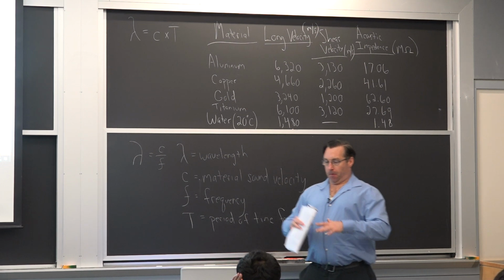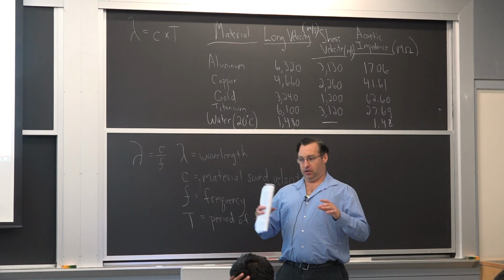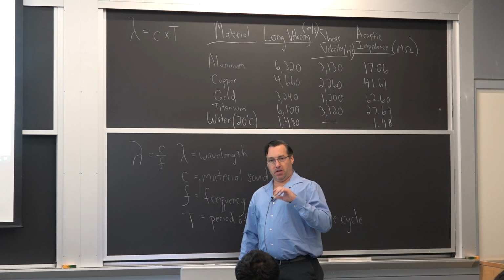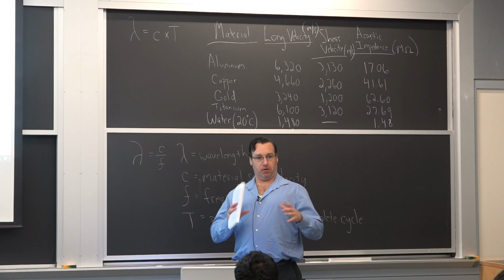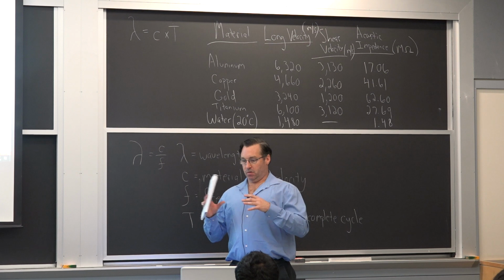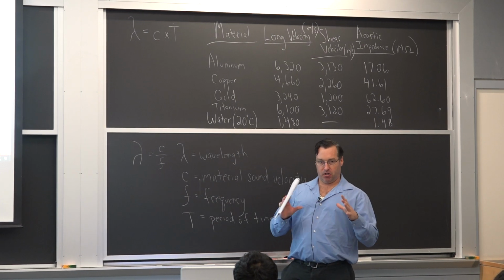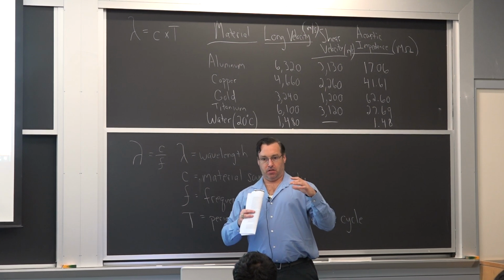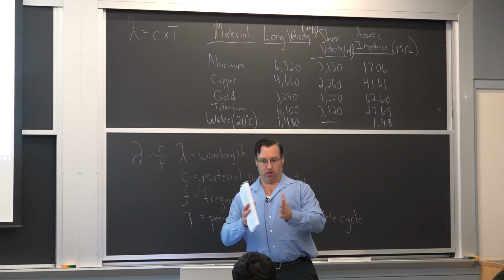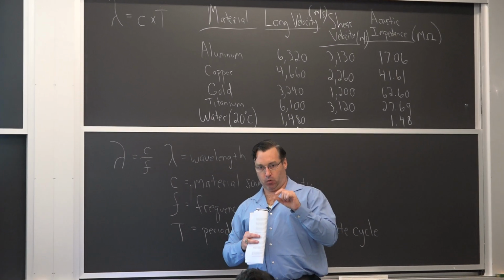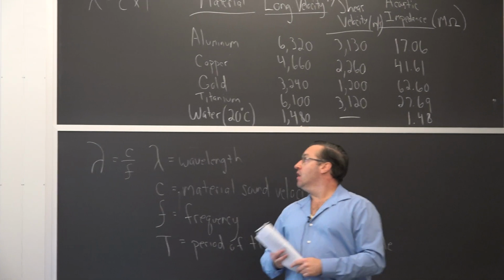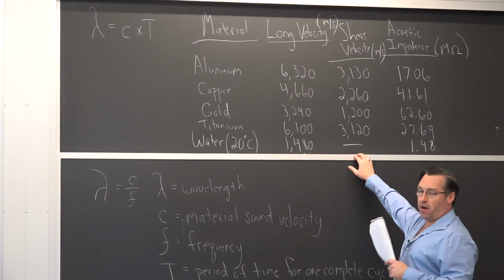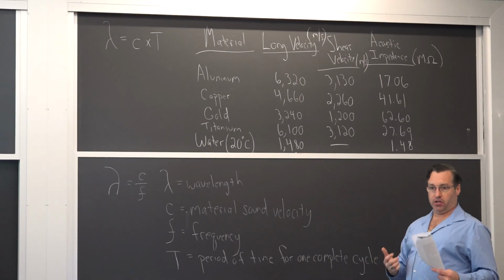So for the material scientists and mechanical engineers, the way I can explain it is if you know the material you have, if we go down to where the grain structure is, if we're talking about separate grains in a material versus single crystal, what happens is as you send those sound waves into the material, they're going to scatter, attenuate, interact at that nano level, okay? That's where it becomes necessary to know the factors of the material under test, all right?